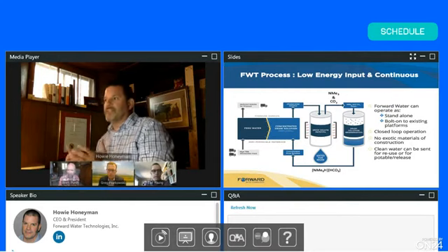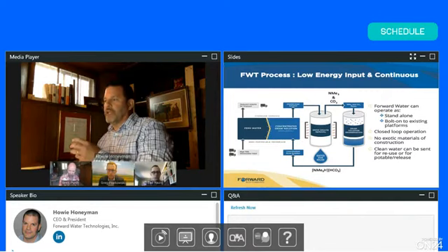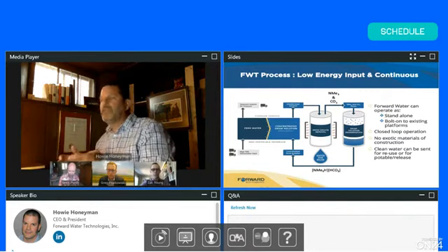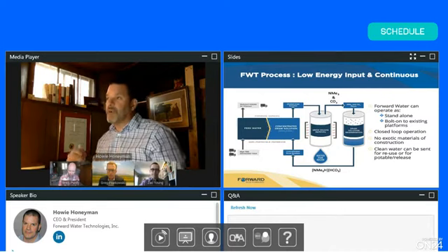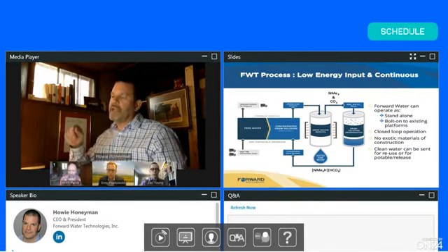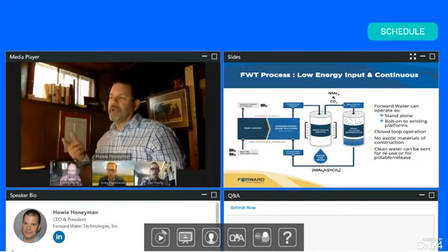Ultimately, once that solution is exhausted and has reduced the volume of the feed water, the feed water goes off for final disposal, and that now diluted draw solution gets processed by a little bit of heat being pumped into it. That causes our proprietary draw solute to turn into two gases, and they simply bubble out of the now clean water, leaving behind water that can be sent straight for reuse. And we capture those evolving gases, reconcentrate them in a second step, and reuse them in the front end of the process.